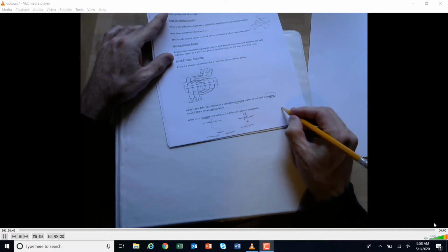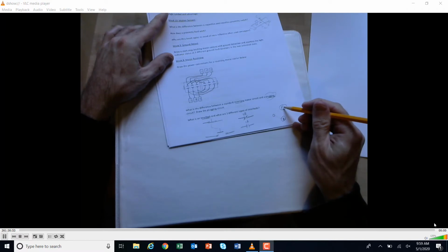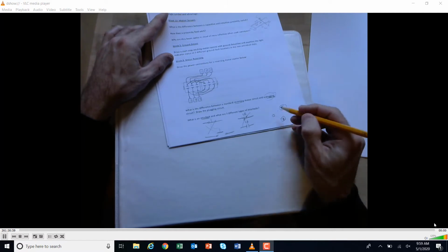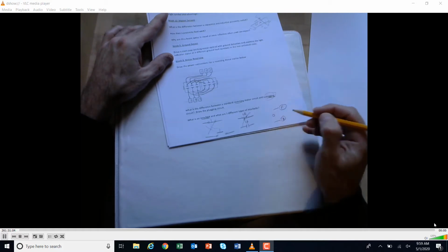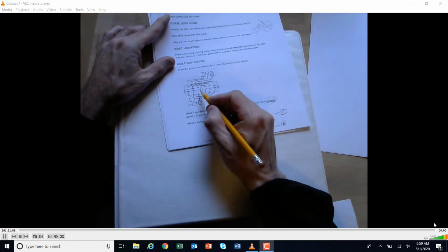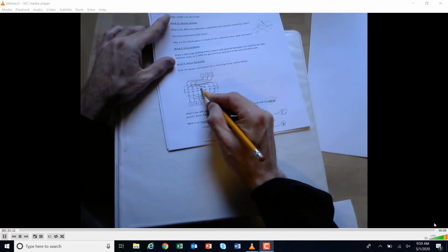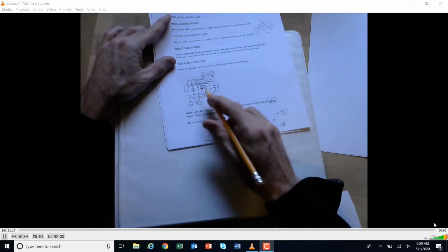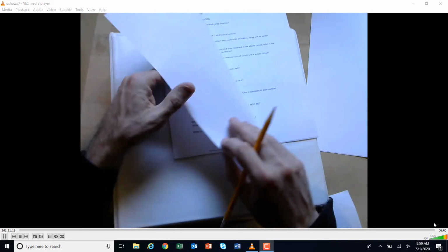And then the other one we had was the mechanical interlock, where you had the forward and the reverse, and you had the little line there indicating that they were mechanically interlocked. So even if you tried to energize them, if for some reason these failed and both of these got voltage to them, they're mechanically set up so that you can't close the contacts forward and close the contacts reverse at the same time, because inside of here there's a mechanical device that prevents it from sliding or from energizing both at the same time. So those were our interlocks.